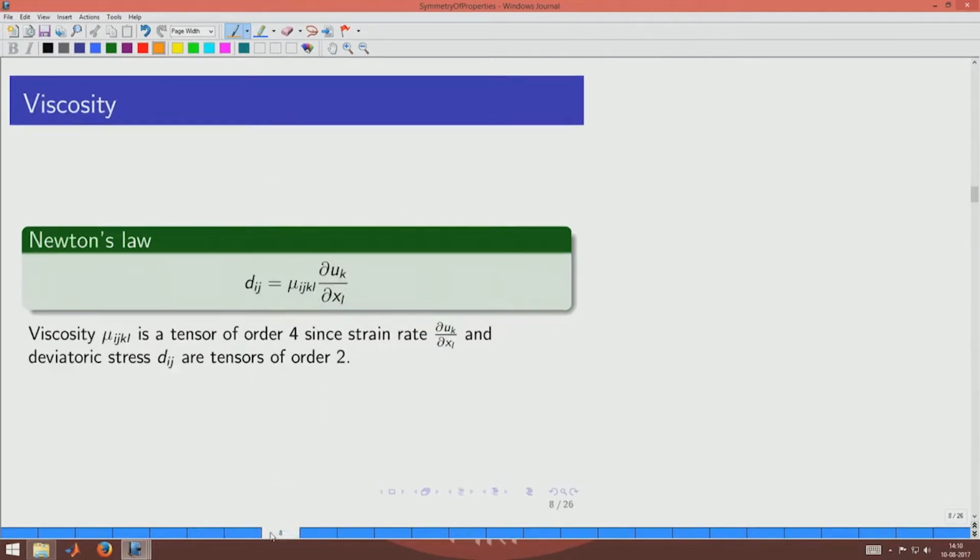Okay. Now, viscosity is basically a resistance of one liquid layer from being moved with respect to another liquid layer. Usually it relates to the shear stress that is applied, so that there could be differences in the velocities that are created. This kind of relationship connects the velocity differences on one end and the shear stresses on the other end. Velocity differences are expressed as velocity gradients, and the most generic form of a velocity gradient would have different indices on the numerator and denominator. So, you have the possibility of a second order tensor, which is the strain rate given there.